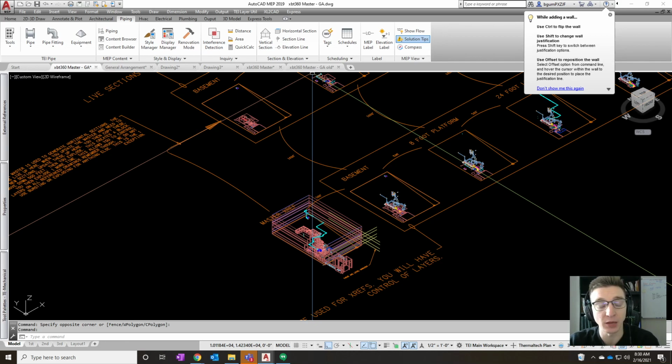AEC objects are things like pipes, ducts, conduit, cable tray, walls, doors, columns, as well as multi-view parts. If it's one of those objects, global cut planes are going to help you to cut a cut plane and isolate things such as the first floor, second floor, third floor. And it's going to give you a framework to work around when you're trying to generate 2D drawings.